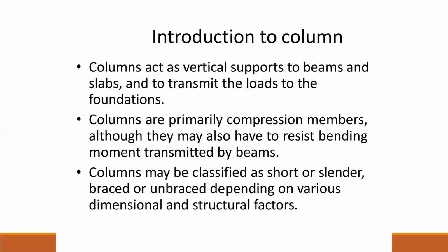The second one is that columns are primarily compression members, although they may also have to resist the bending moment transmitted by the beam. As I said to you yesterday, the beams are only subjected to flexure, shear and axial loads, but in the sense that axial means it is less than 0.1.